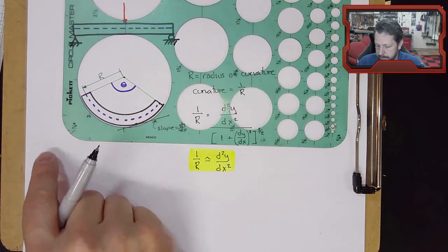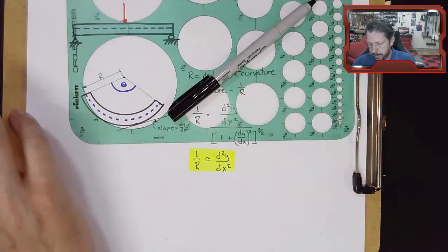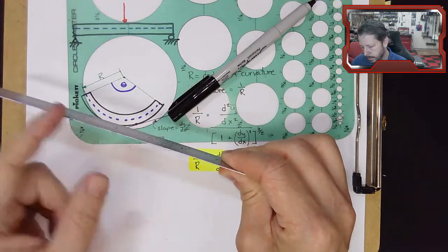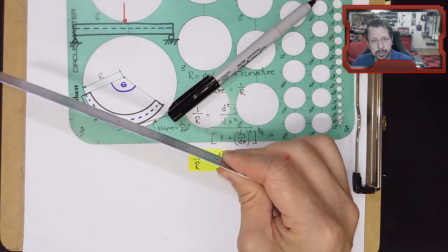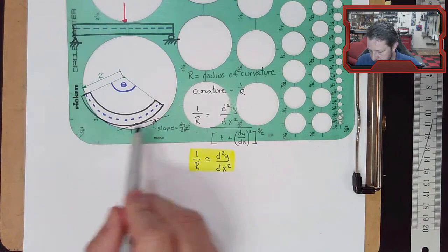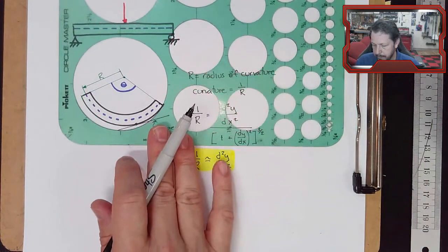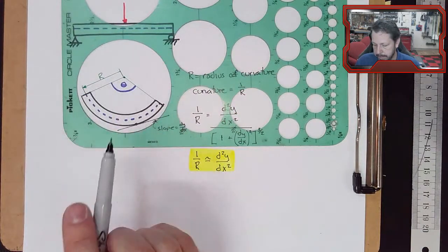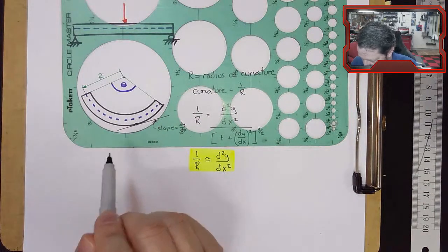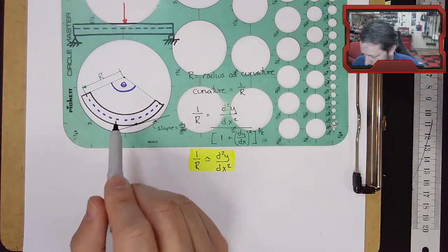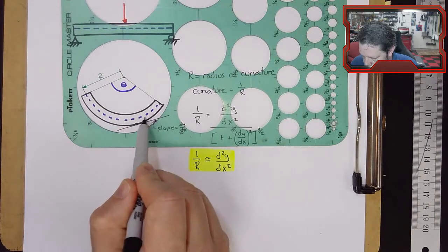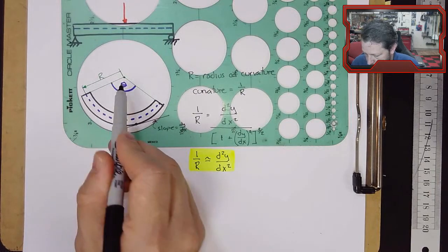Maybe you've got it bent into an S shape or whatever, but there's an arc here and another arc here, all these little arcs put together. So this is not unreasonable for what we're thinking about. The idea is not unreasonable; the exaggeration is unreasonable. So this length of the neutral axis here is an arc length, r theta.